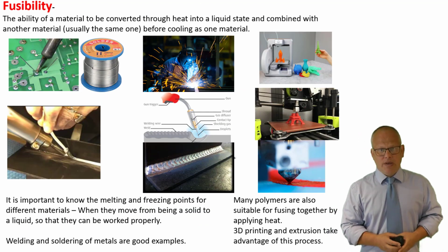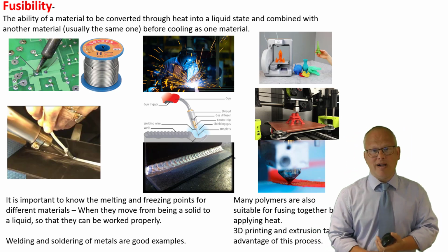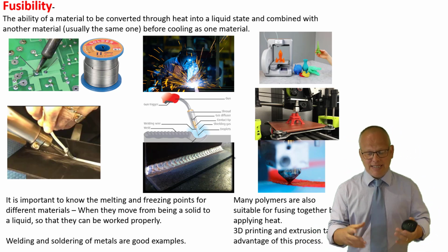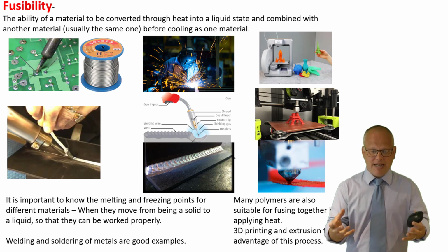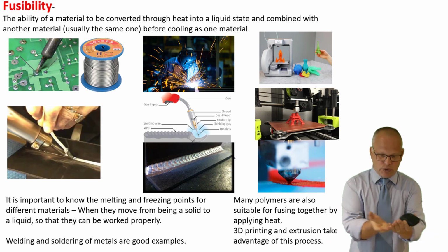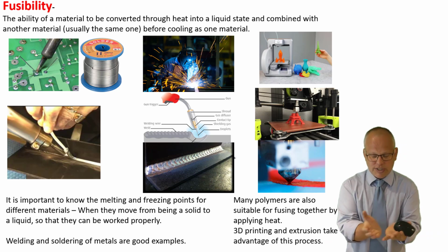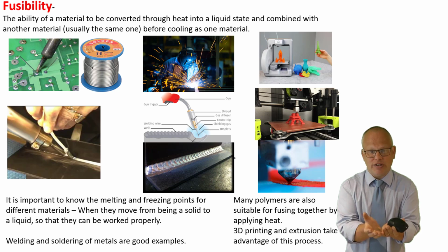Fusibility. A perfect example of fusibility is welding. That's been around for donkey's years. Basically, you get your mild steel, you heat it up to a point where it becomes a liquid, and you join another piece to it in its liquid state, and then when it cools, those two materials are indistinguishable from each other.